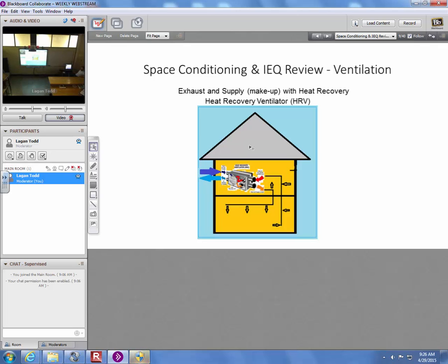In a climate like ours, where your lowest design temperatures get down to negative 20, and even negative 30 if you're over at Bozeman, at those coldest temperatures, if this heat exchanger is doing its job, you might bring in negative 20 air, and what comes out of the HRV is warmer than, say, 30 degrees.